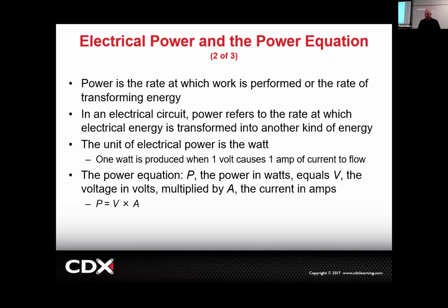So remember I was saying there'd be some justification for increasing the automotive voltage a little higher, because it would help to mitigate some of the corrosion, or any unwanted resistance will have less of an effect if it was a higher voltage. Well, now I'm going to really trip you out. If we need things to do power, which is like work, right? It's volts times amps. If you have 12 volts and you need 12 watts, that means you would need 1 amp to do the work.